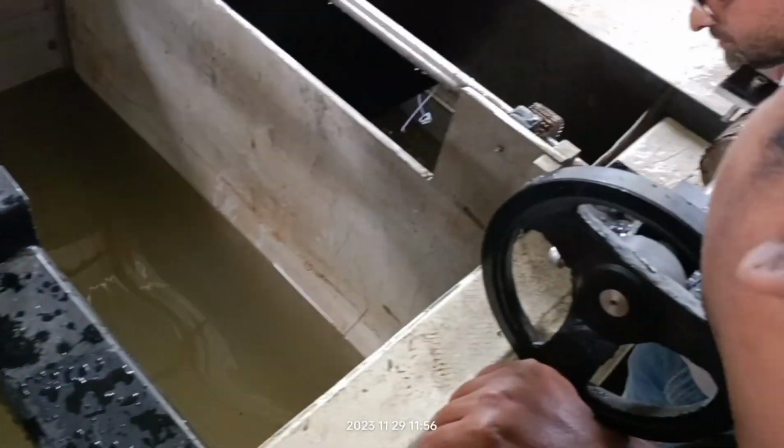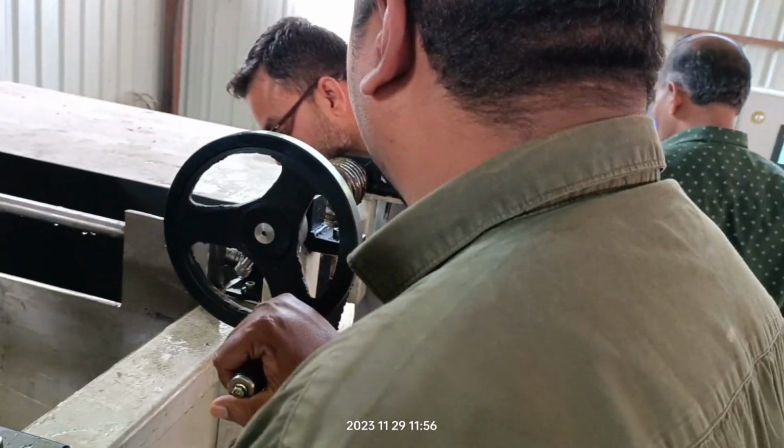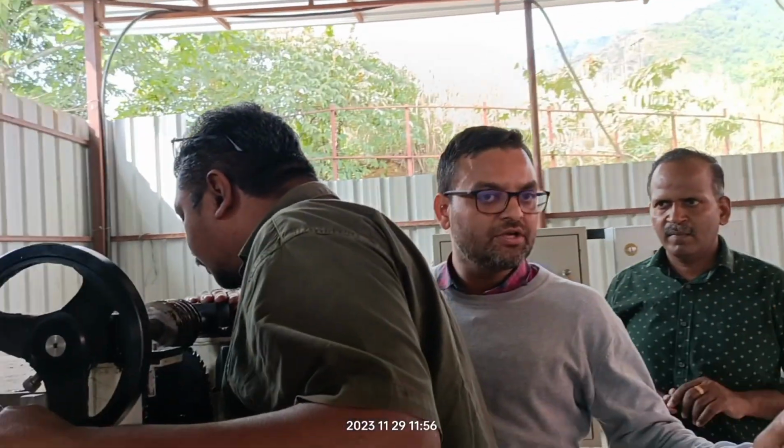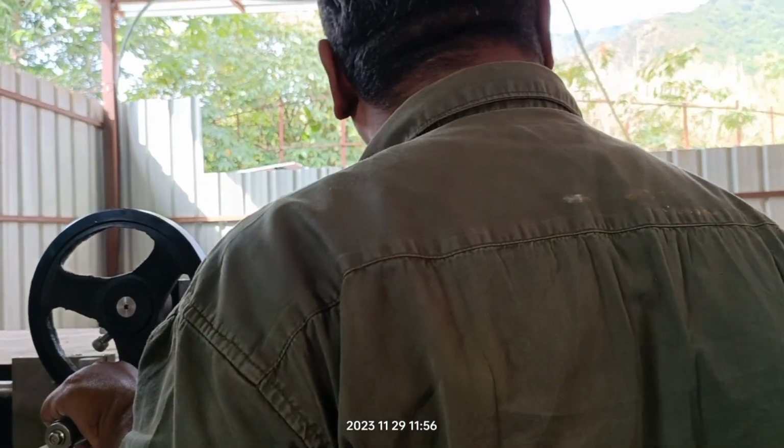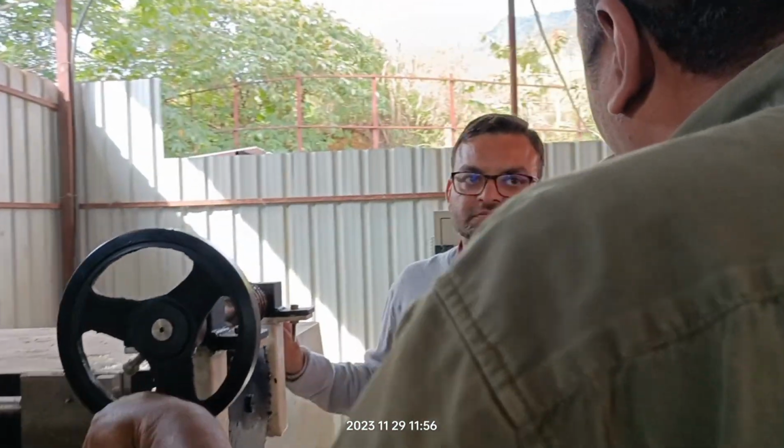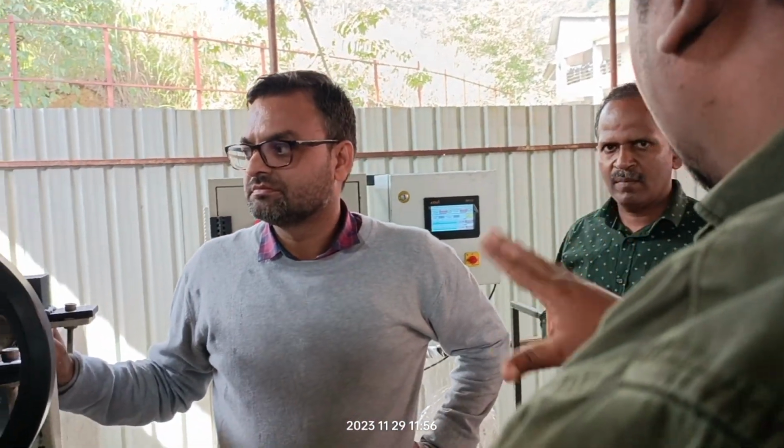Another thing will be from the bottom, too much water will be moving. For your time, Albert, I will apply some silicone gel. No, first you provide full gel. The life of silicone gel is only 1 year. I cannot again go and keep on applying silicone gel, because it has to be properly removed and then you have to apply.